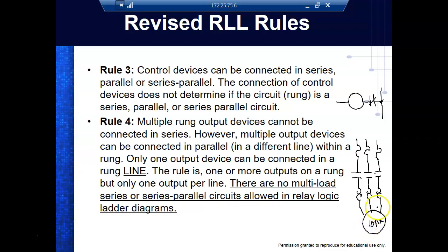When we start it, let's say on the low end, it's going to try to pull 60 amps just to get it started. But my fuses are going to have to be rated over 60 amps. It's usually 150 to 155%. So these things might be rated at 70 amps.